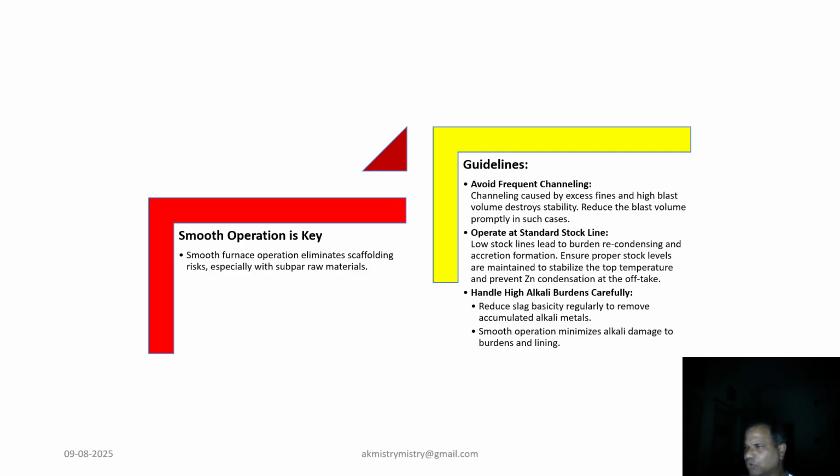Instead, use low pressure artesian flow to supply cooling water while being extremely careful to avoid any leakages into the furnace. Properly manage cooler maintenance. This involves stopping the water supply during furnace shutdown and restarting it before blowing in to prevent cooler burnout.